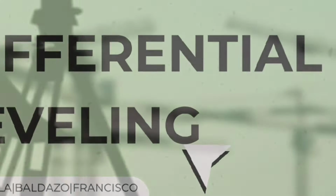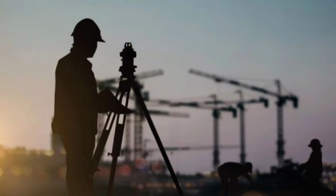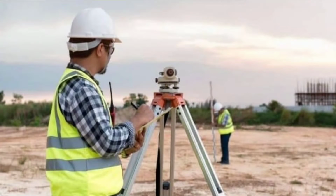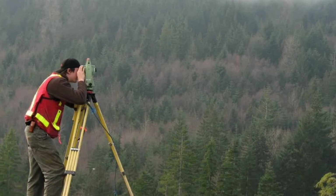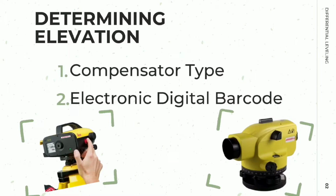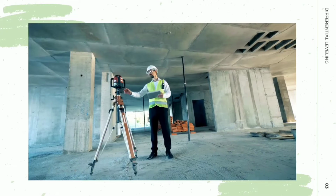Differential leveling is the process of determining the elevations of unknown sites by measuring vertical distances from a known elevation point. The two most prevalent ways for determining elevation are, first, a compensator type, automatic or engineering level, and level rods, and second, an electronic digital barcode leveling instrument with barcode rod.